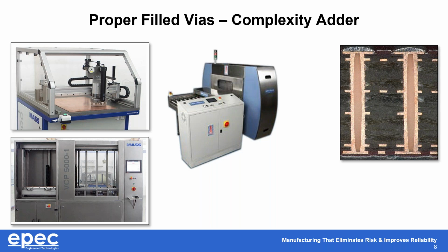The challenge is that that's another one of these processes that takes a whole lot more time than anybody recognizes. If it was nothing more than just trying to squeeze the material down through the vias and being done with it, that would be one thing. However, you have to start by pre-baking the material. Many times it's over an hour to get the laminate to the temperature so that the material will flow through, right?